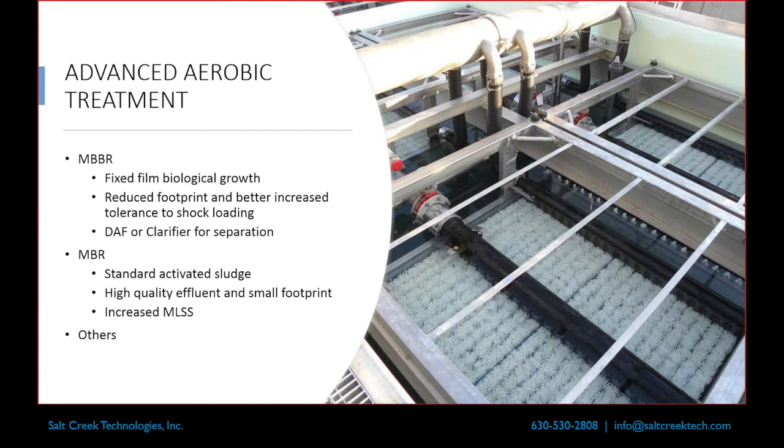So then on MBR, which is a membrane bioreactor, like John mentioned, they'll use a standard activated sludge aeration tank. And then after that, for the separation device, you'll use a membrane system. Typically, it's an ultrafiltration membrane. Here's one type where you can see the straws that are standing on end, and they extend down about 6 feet or so to the bottom. The water gets pulled in through the straw, and the biological material gets retained on the outside here.